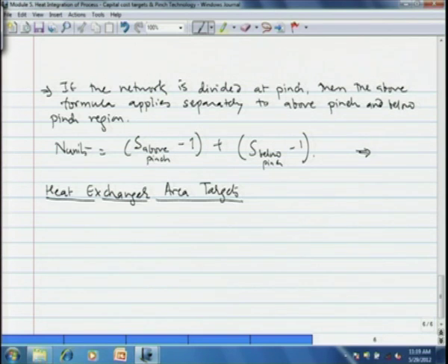The composite curves themselves contain the necessary information to predict the network heat transfer area. To calculate the network area from composite curves, the utility streams must be included with process streams in the composite curve to obtain a completely balanced composite curve, basically the same procedure as we have seen before, but with inclusion of the utility streams.